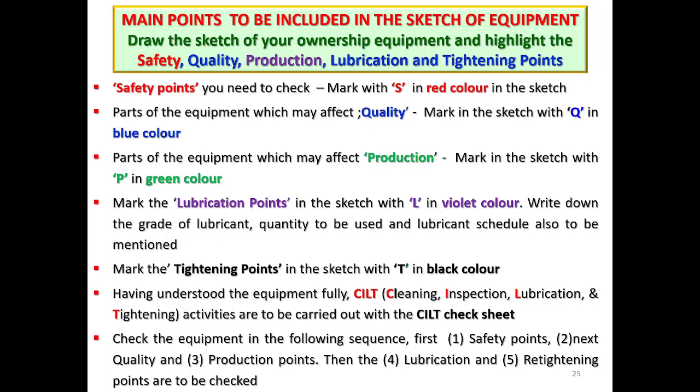Having understood the equipment fully, then start CILT activities. In the field, check your equipment in the following sequence. First, check the safety points. Next, quality, production, lubrication, and lastly, the retightening points.